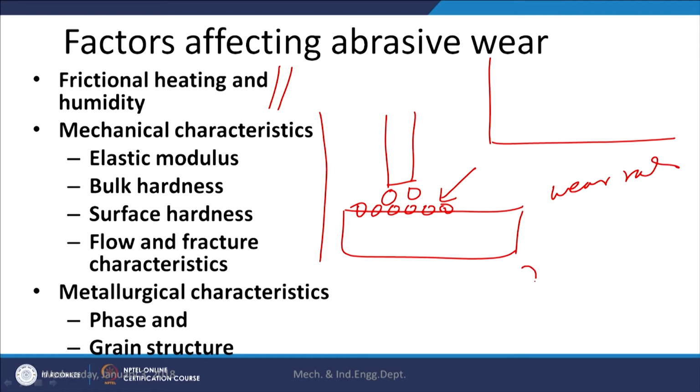So, as compared to the dry environment, a humid environment will cause a greater abrasive wear rate if it forms some soft compounds on the workpiece surface.